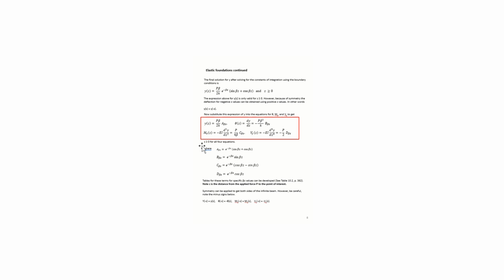Now, one thing we want to be careful with here, based on the symmetry, is the displacement is completely symmetric. However, the slope is not, it changes, so theta of negative z is equal to negative theta z. The moment then again is symmetric, and the shear is like the slope, where V of minus z is equal to minus V z. And again we saw these tables where we can look these values up.